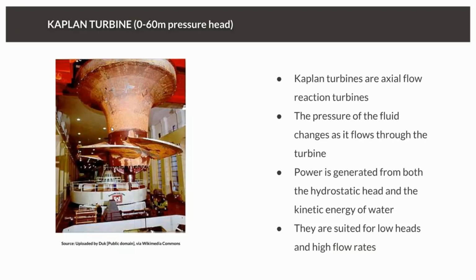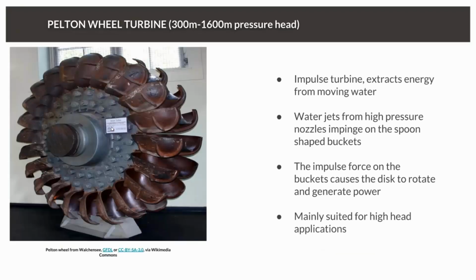But if you think about using these in an opposite way, it's basically the same as a propeller design, right? So they can move very, very fast, and they can move a lot of water, and that's where they're good: very high speed flows, but low pressure. The total other end of the scale, if you check out the pressure head at the top, that's 1.5 kilometers of water that this could have above it and not get destroyed. This is where these are good.